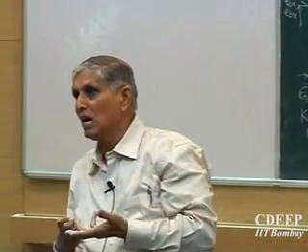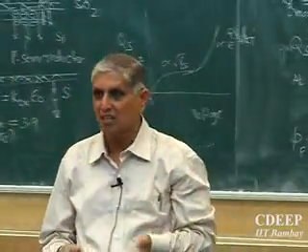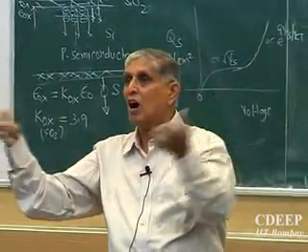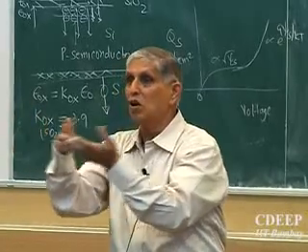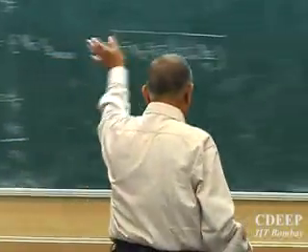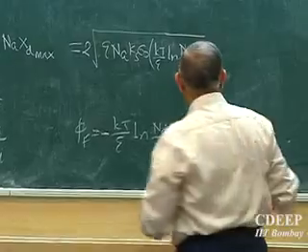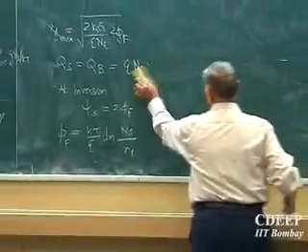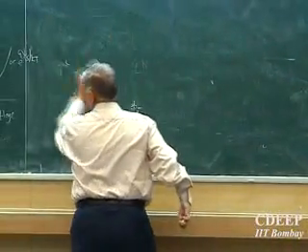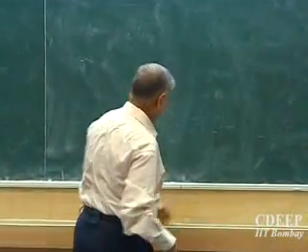Internally, how they divide, I don't know. I can measure capacitance at best, but I don't know how they divide. So I must now figure out how they really divide. Because I am applying VGS, how much is the semiconductor bias and how much is the oxide voltage. So I write an equation. Please note this down. Maybe I'll rub it off now. This figure I'll keep because that will help.